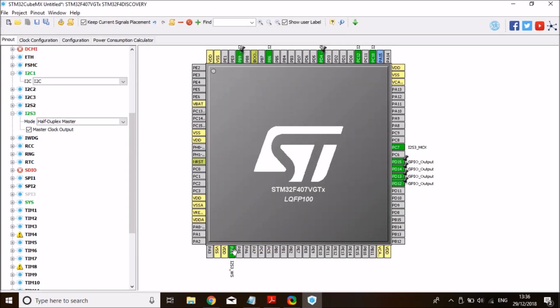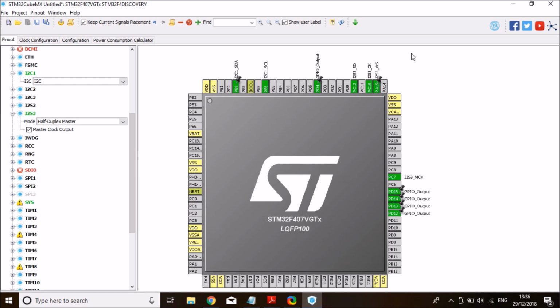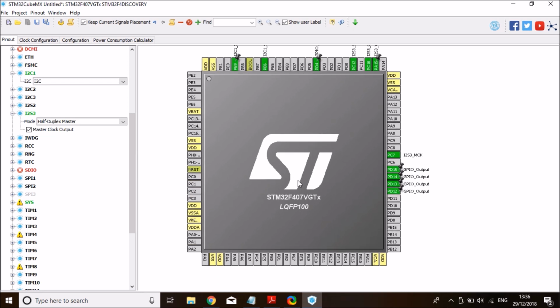Click on control and then left click on the mouse and drag it over to the alternate pin highlighted in blue. So any other pin really, because we don't need the word select pin for this analog mode. And instead on PA4 we can enable a DAC output on the STM. Alright, and that's it. That's all the pins we need on the STM board.